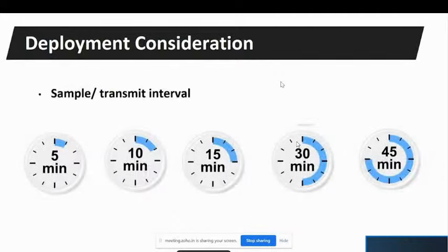Another thing is what is the sample time, because Kaushal sir already told us that LoRaWAN is not for high speed data connectivity. It has a very limited payload, and it has a very low duty cycle. So we cannot send data very fast. It cannot be in seconds or in milliseconds, but definitely we can send data at a regular interval of 10 seconds, 20 seconds, 50 seconds.